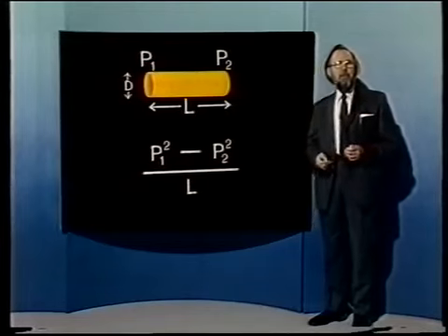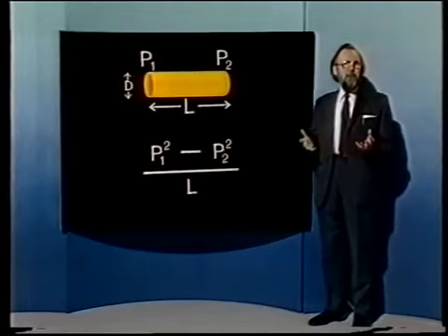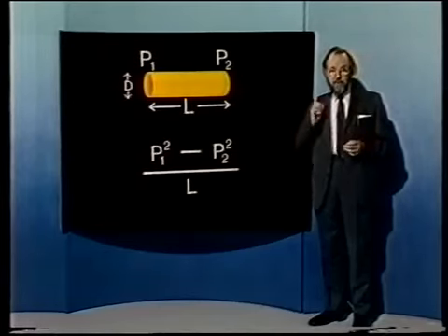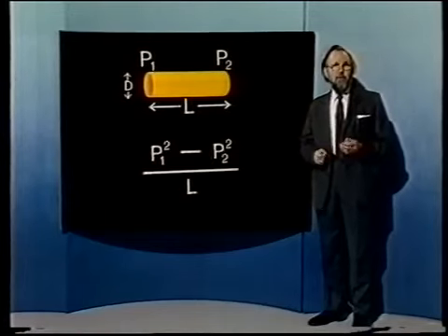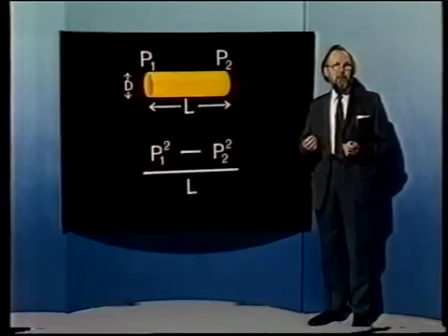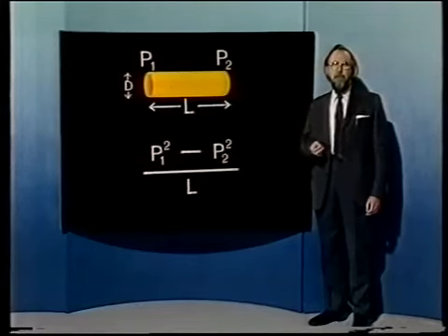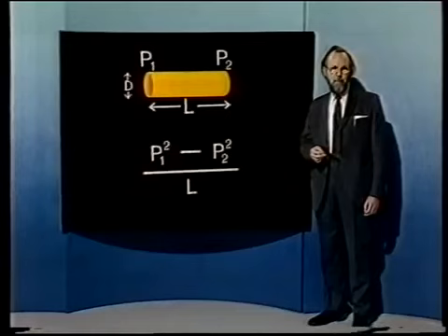Now we can reduce the cost by choosing a small diameter d. But you've got to suppose that the pipe is going to be required to carry a certain flow of gas. And this is the catch. You see, if we make d too small, then the pressure squared difference may have to be increased, probably artificially, in order to maintain the flow. And that means using compressors to increase the pressure. And they're expensive, both to install and to maintain.